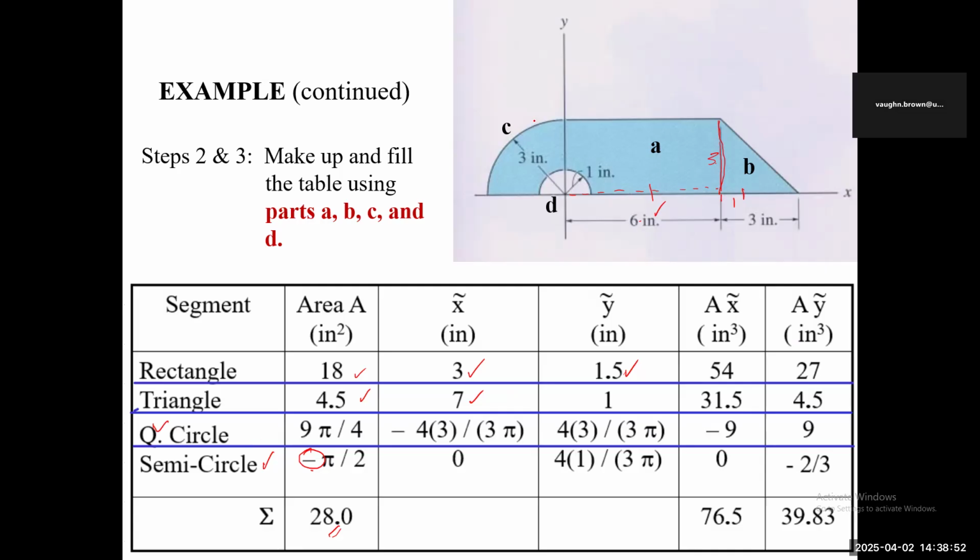The quarter circle. So for the quarter circle, what rules apply? What's the formula to get the quarter circle? The X distance is this. And watch this carefully. Will this distance be a positive distance or a negative distance? You want that X bar and you want the Y bar here. This distance here is a negative distance. I've gone over here. This is the negative X axis. So the quantity cannot be positive.